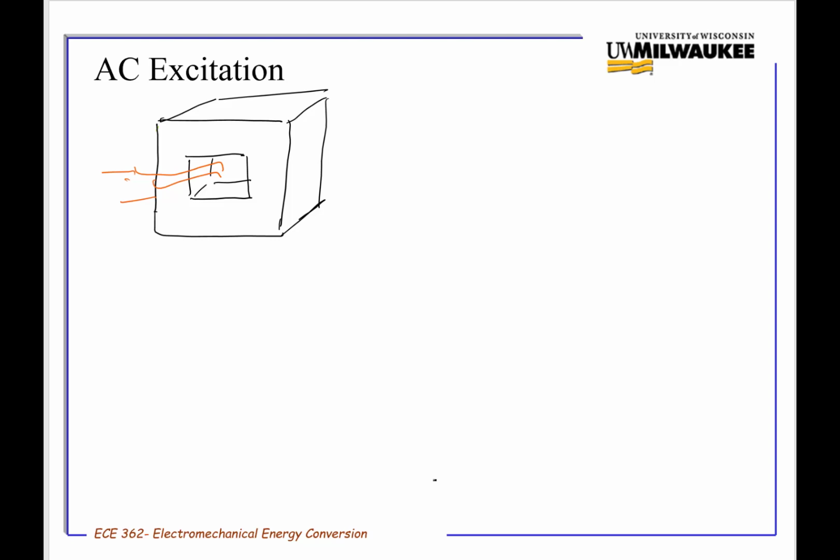I went once and I saw how they set up, I believe it's called an Epstein test setup, where they take a core sample and they apply a variable AC voltage, which puts a current into the coil, and then they excite a flux in the coil, an alternating current flux, and then they're able to derive the BH curve from this test. And we're going to actually describe that test right now.